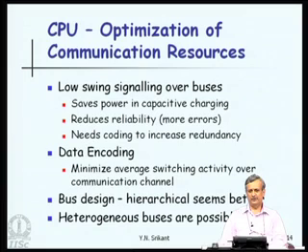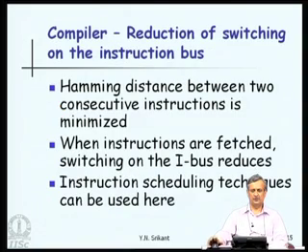So, if we have communication which is very urgent, we can send it over the faster bus even though it requires more energy, and if there is communication which can be sent in a relaxed manner, it can be sent over the slower bus which requires less energy. So, that is the principle behind the heterogeneous bus operation. We are going to see that a little later.